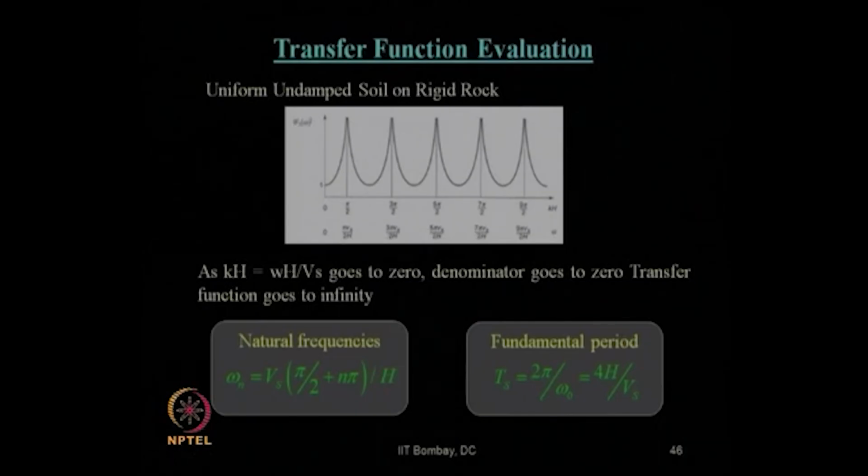Okay. Now, can you see what we mentioned earlier as a thumb rule, that we typically use to obtain the fundamental period of any soil site? This is the way we can calculate the fundamental period of any soil site, that is 4h by V s.